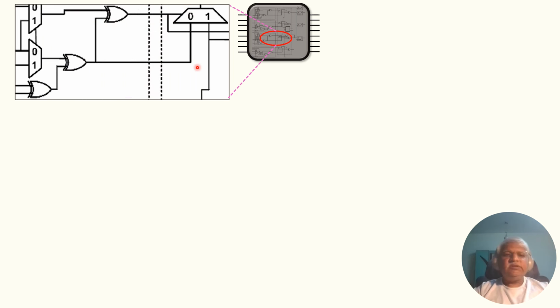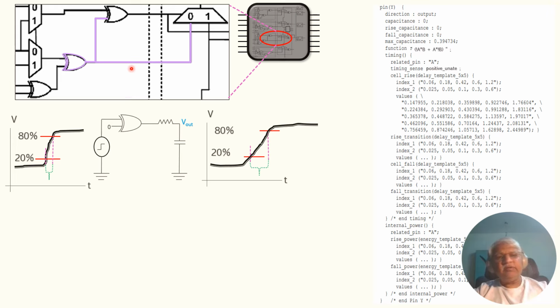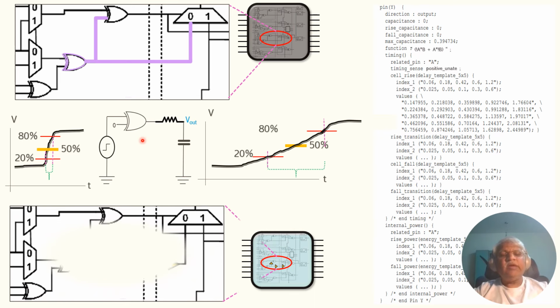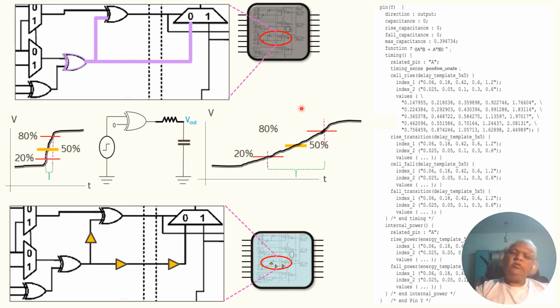In one situation where the input design has a large load, the synthesis tool could have done something in this fashion. It has added some buffers in an asymmetric manner. It need not be symmetric, like add two here, add two there. It has already evaluated which is the better option. So this is one part of the manipulation possible in design rule checking.